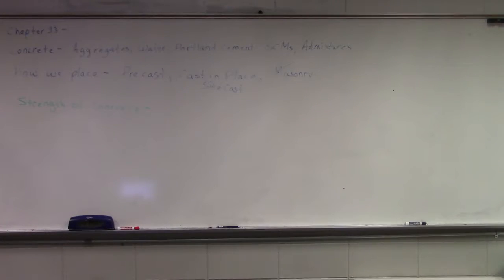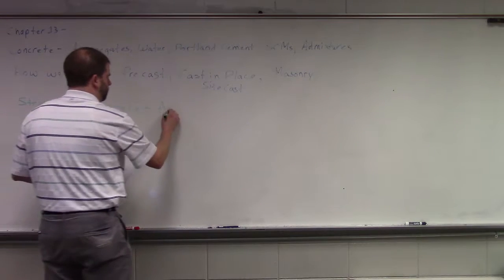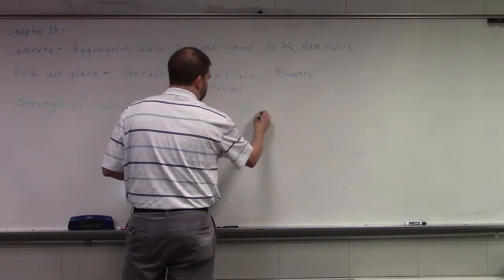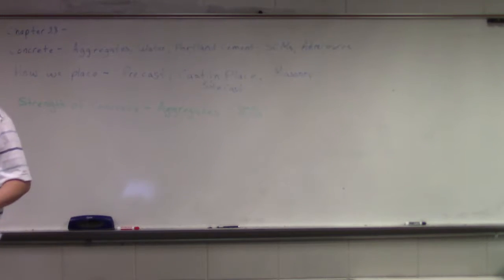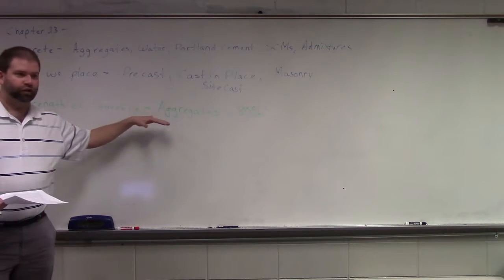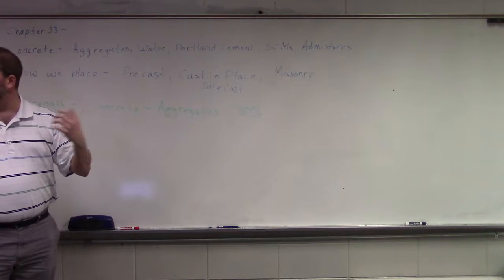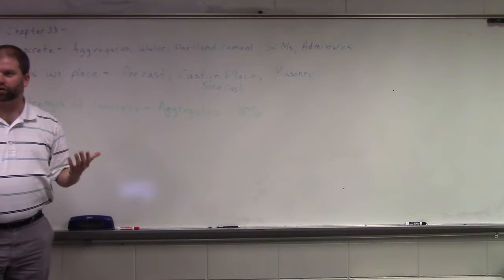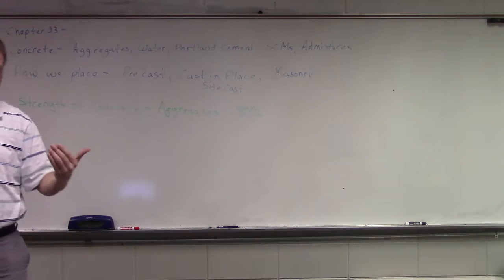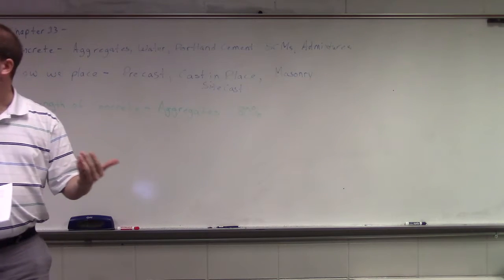And so what are the major items that they talk about as far as how we can impact the strength of our concrete? What's the biggest factor that drives it? Our aggregates, right? Remember that our aggregates comprise about 80% by weight and by volume of our concrete. Okay, so that's a large percentage of it. And for the longest time, aggregates were just used as filler. We just needed it to take up space. About 50 years ago, people started doing research and discovered that if you increase the quality of the aggregate, you increase the quality of the concrete. So now that becomes a very important factor in determining what we're going to use for our concretes.